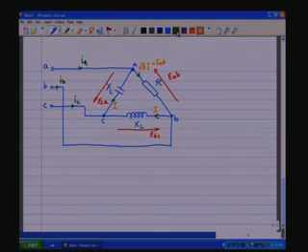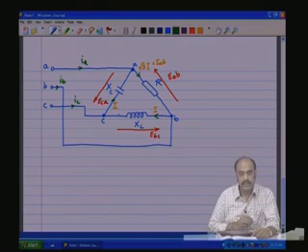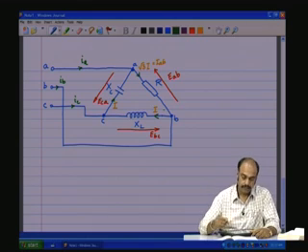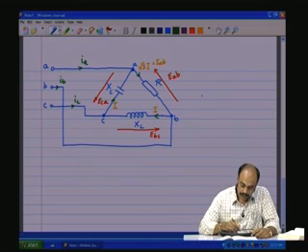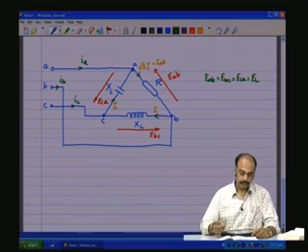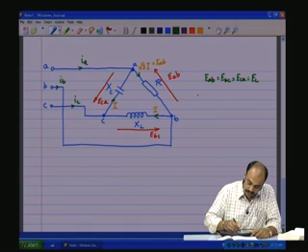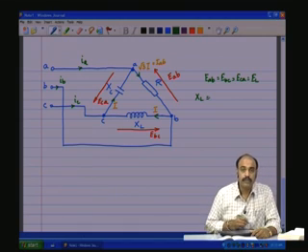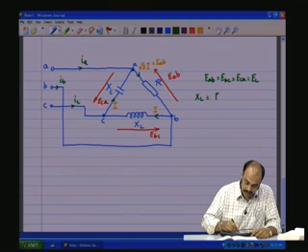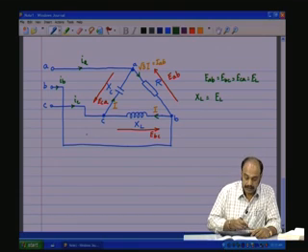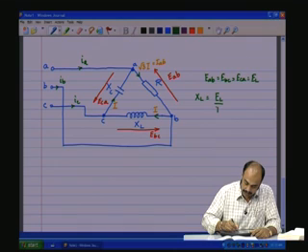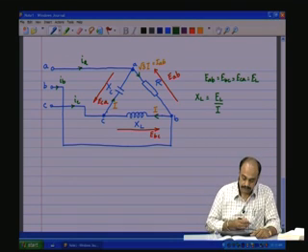So, now we can find out what should be the reactance which will give this kind of a solution. Now, the effective values EAB equal to EBC equal to ECA equal to E line, for a balanced source which is applied, and therefore XL is E line, the voltage across the inductor, divided by I, the current which is supposed to go through that.